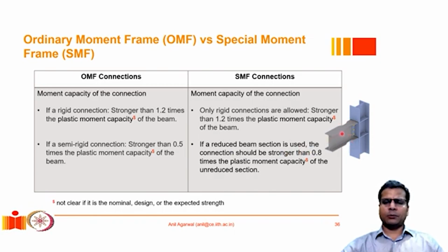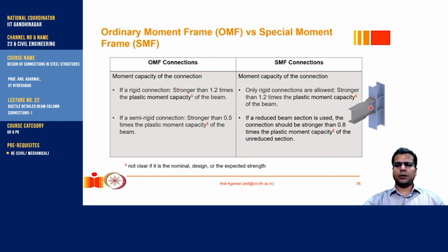Here you may see that the beam cross section is uniform almost up to the point where it is connected to the column, but just before that it is reduced artificially in a very smooth manner. And the idea here is that we want to artificially create an area which can be designated as the hinge area, and when a high moment demand comes, it does not produce a failure here, but it should produce a large amount of yielding in this region.